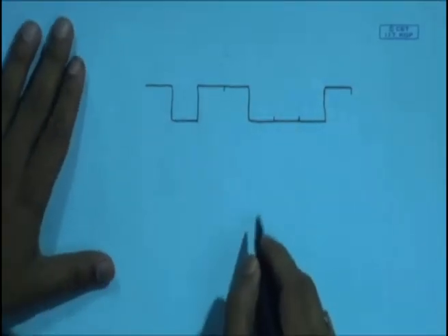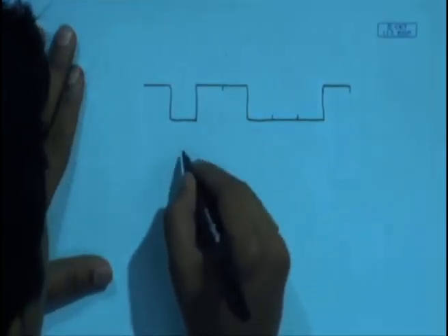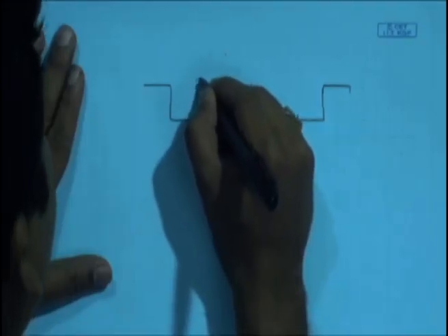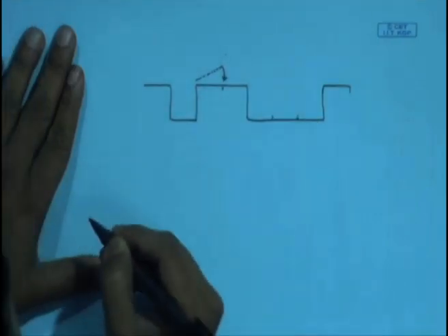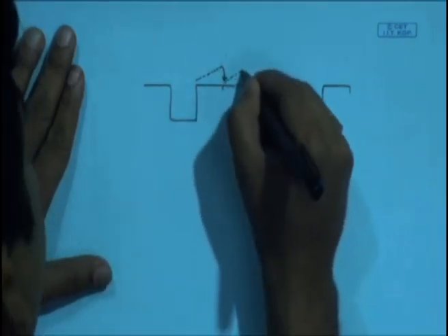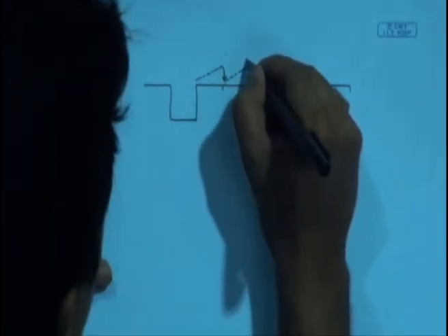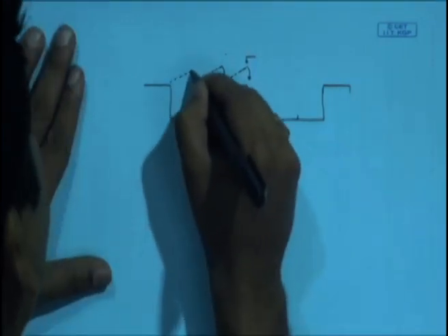If we take matched filtering for rectangular pulses, typically we would have the integrate and dump circuit, which can be graphically represented through an integration followed by a dump operation, which goes on happening for every symbol duration, and the values are read off at the peak where the symbol duration ends.